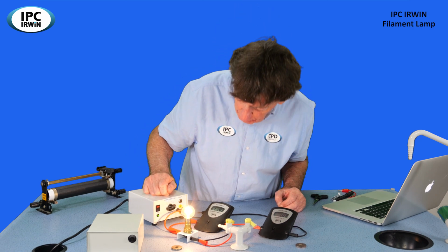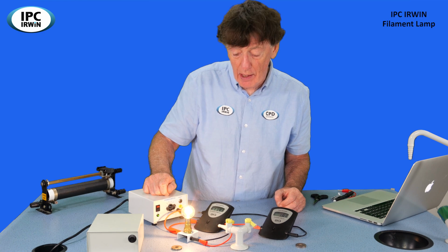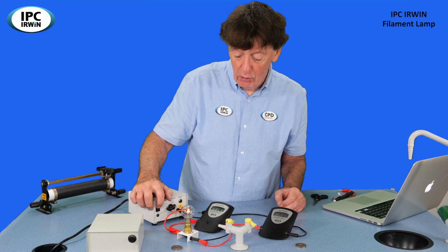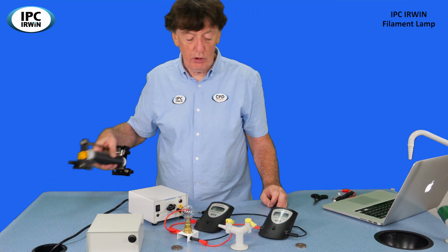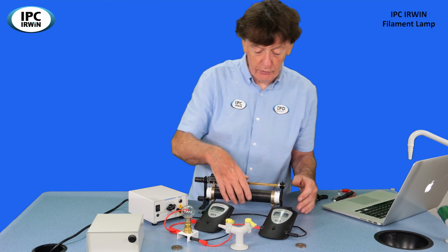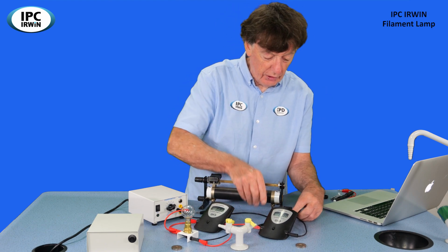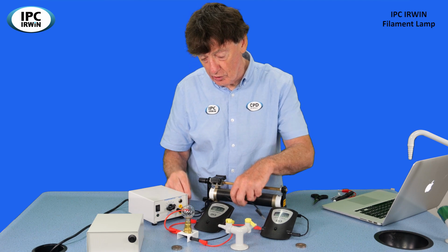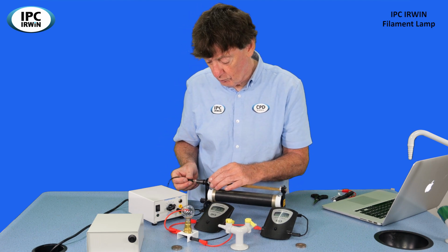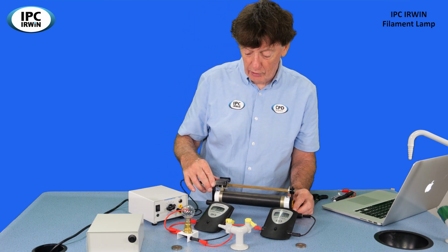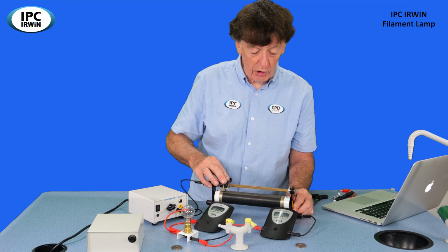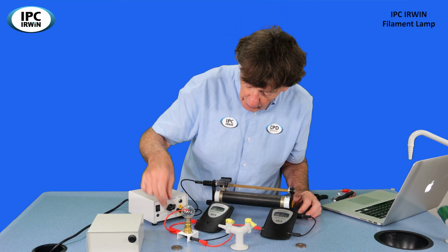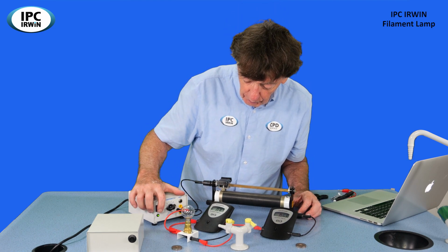Now that will only give you 6 pairs of readings. So what I'd like to do is show you how we can use a rheostat to provide a much smoother change in the readings. So we're connecting this in series. We're coming into the top on the slider and out there. We'll set the output at 12 volts.